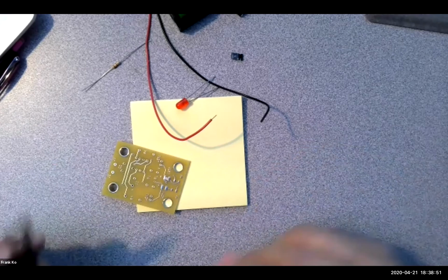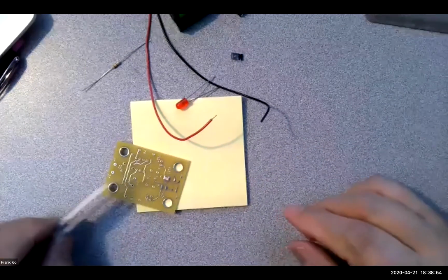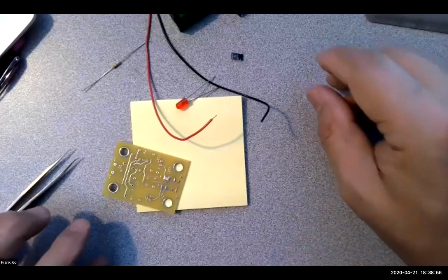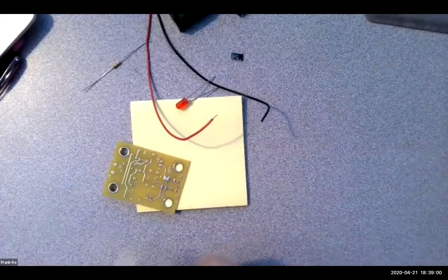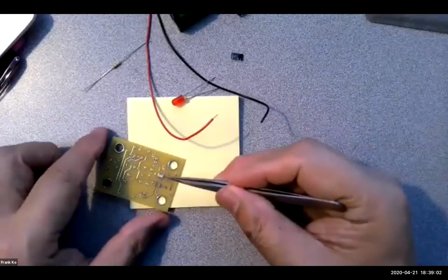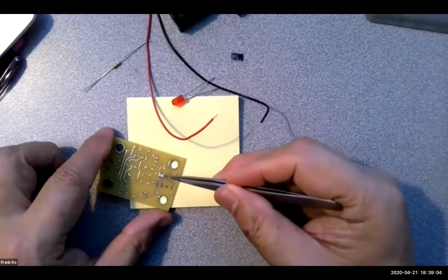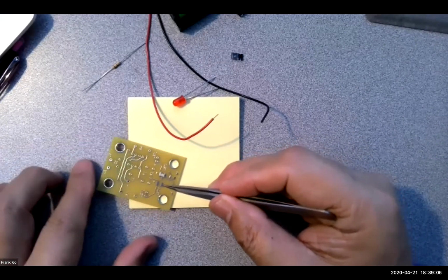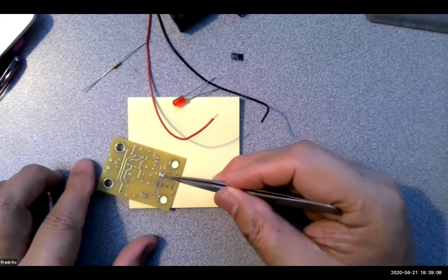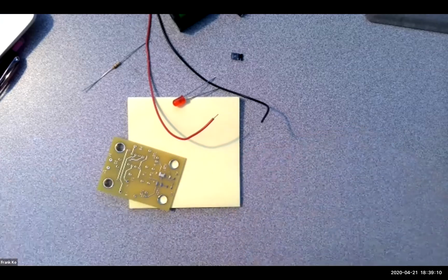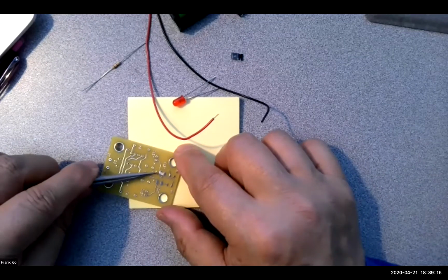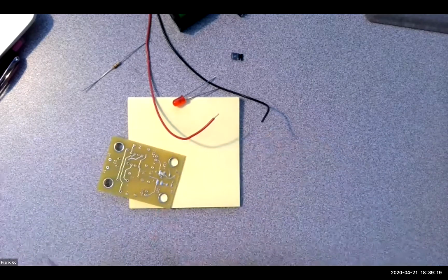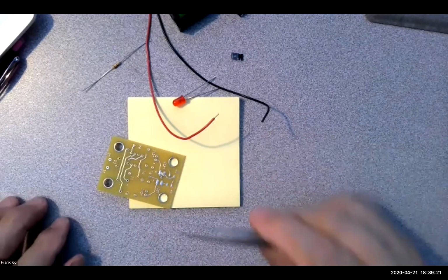My recommendation is to have something weighted to hold it down, like an eraser, because you're going to heat up gently with your iron over this side, and whatever solder you've already put on the pad will just melt to make connections. Then you put your iron gently on this side without moving the LED, and melt the solder that's already on the pad. So the procedure is that method.